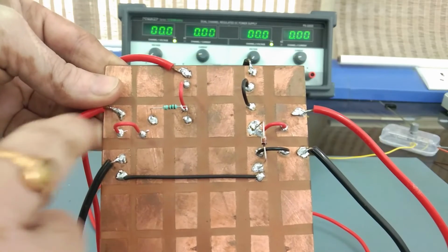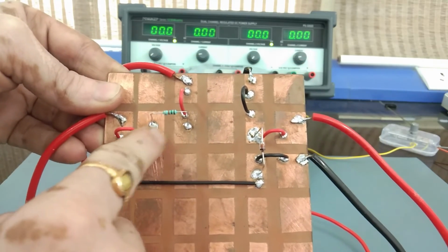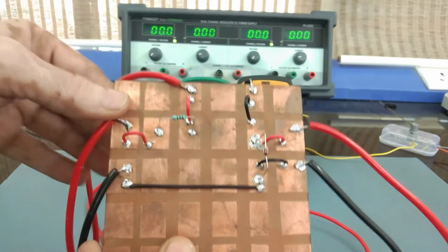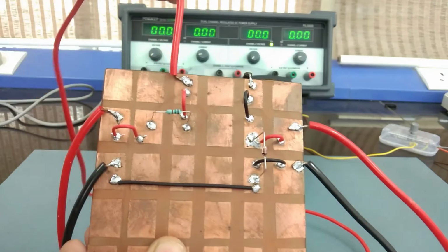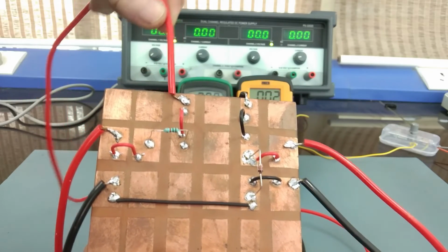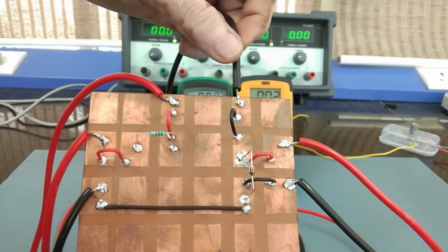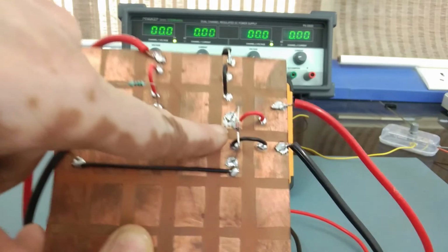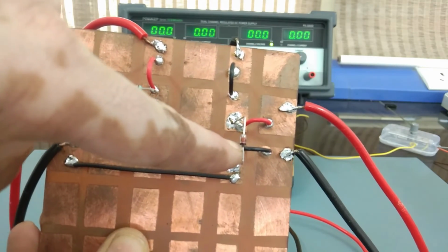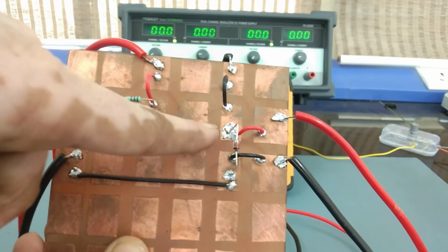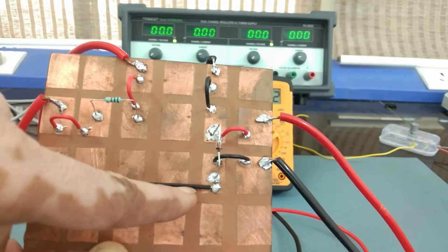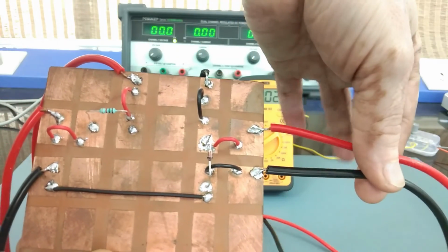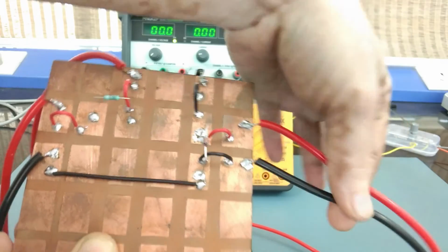The positive terminal is connected directly to a series resistance that restricts the current through the Zener, and you can find from the series resistance we get this terminal for the ammeter, and the negative terminal of the ammeter is connected directly to the anode of the Zener. You can see the black patch is on the common side. So now the Zener is in forward bias. The voltage across the Zener, you can see the parallel tappings are there. The voltage across the Zener is measured through these two terminals.